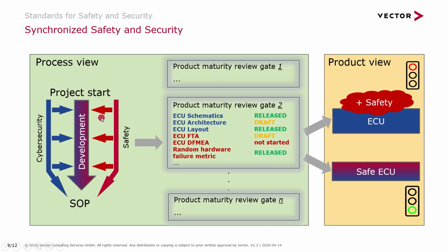For instance, you do an initial systems analysis with respect to what are the risks. That means we have a HARA from a safety perspective and a TARA from a security perspective, which we then align and see what would be the different risks, how do we prioritize the risk. Then we achieve a safety goal, and we have again a synchronization point, which is, can this safety goal be compromised by a security attack? That would be the next synchronization point.